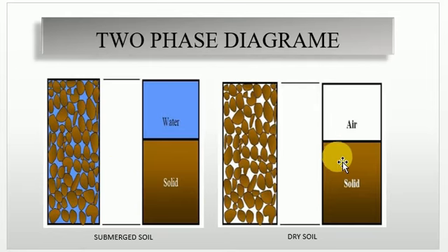On the other hand, if this soil sample is oven dried, right? Because when we take a sample from the natural ground, after that we oven dry it, right? So we will know the moisture content of the natural soil. So here is the sample. If it is oven dried, then it will look like this: nothing, right? Only soil solids, and the voids are totally air voids.